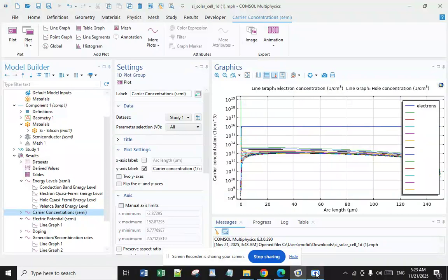Second, mobility, mu, and diffusion coefficient, D, of charge carriers, which characterize carrier transport due to drift and diffusion respectively. The third is lifetime, tau, and diffusion length, L, of the excess carriers, which characterize the recombination-generation processes. And the fourth: band gap energy, Eg, absorption coefficient, alpha, and the refractive index, N, which characterize the ability of a semiconductor to absorb visible and other radiation.